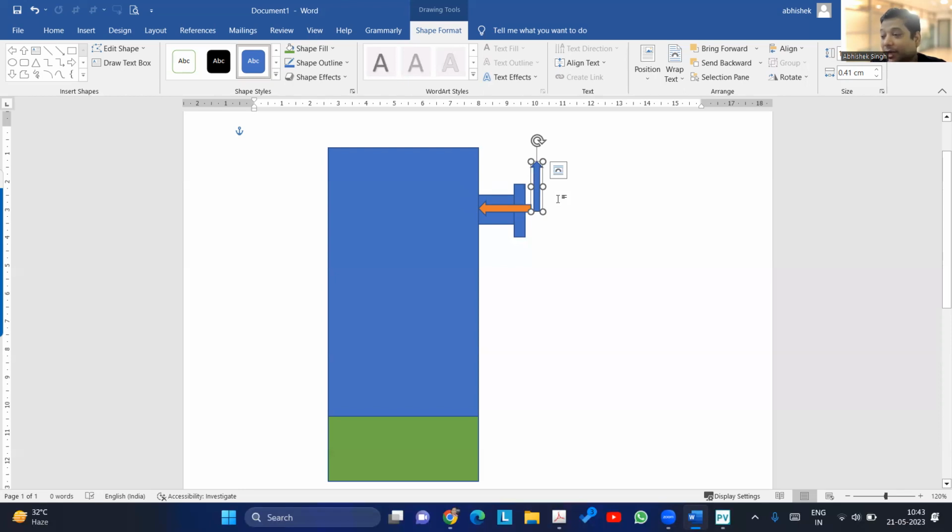Okay. So again, I'll repeat the question. This is my longitudinal load. I'm transferring it from the face to the center line. Why am I doing that? Because we have to evaluate the nozzle to shell junction. We have to calculate WRC, and WRC considers the loads at the junction of the nozzle to shell.